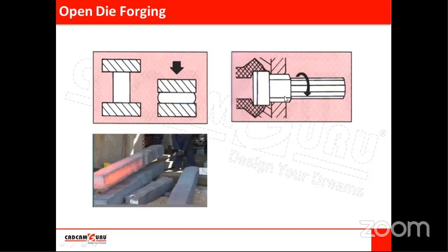If you go to YouTube and see some forging videos, you can see such heavy shafts used in marine applications or in sugar industries. In heavy industries we need heavy shafts. Why use forging? What are the advantages of forging? That part we will see later. But for heavy requirements, heavy power transmission, we need this type of shaft. So here we are using open die forging, right?